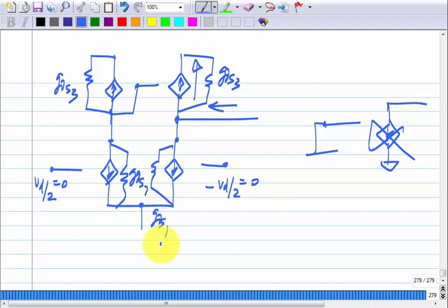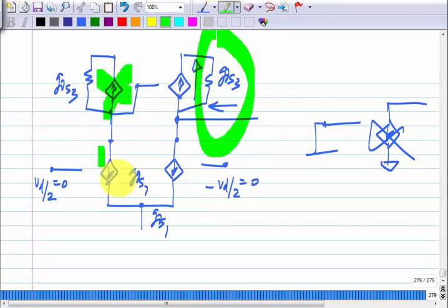Okay, you can calculate it, but again go step by step. First, imagine that only the PMOS transistors have a non-zero GDS. What will be the output resistance in that case? Yeah, output conductance will just be GDS3 because of this, all the other current sources will be off. Anyway, please calculate it and verify it. You can also try it with GDS1. It is actually substantially more messy, although the answer is very simple.